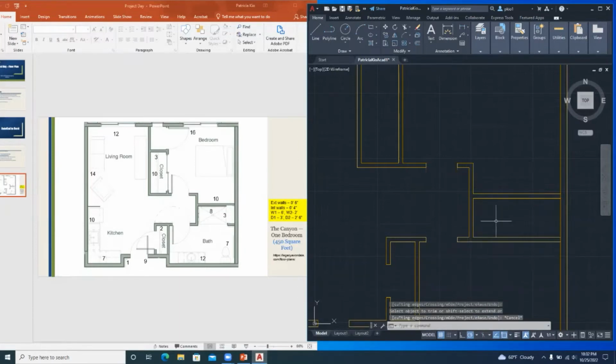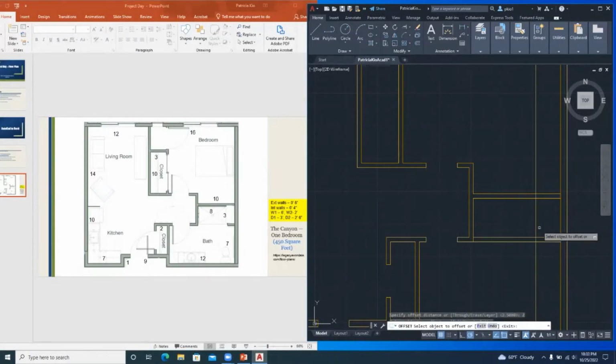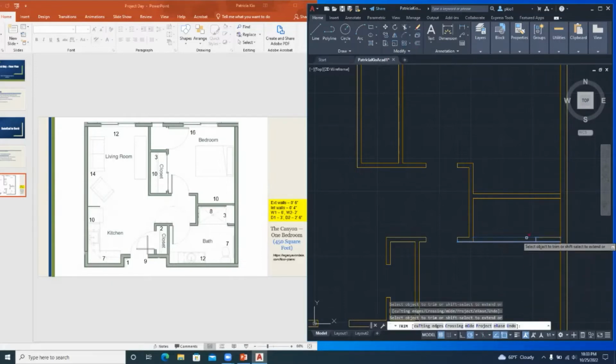And then for this shower, we can have an extension. We extend this wall here, and then we can offset by 2 for here. Get some part of the wall sticking up, then select this over there and trim to this point. Now trim that edge.